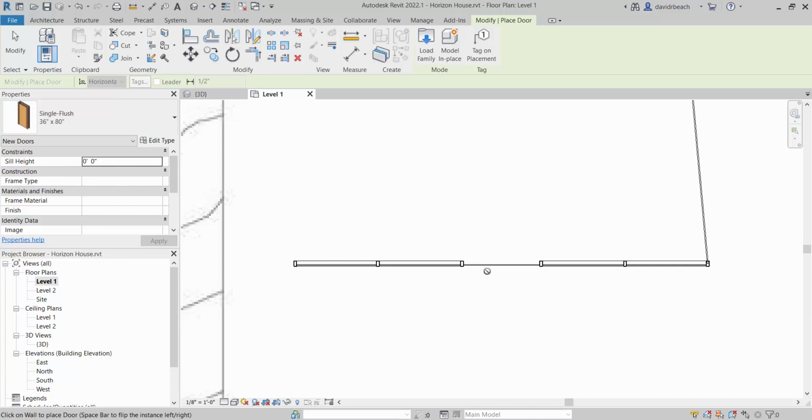Okay, usually if you think about the airlock on our building, those doors in the airlock came from the same company that did the curtain wall door, creating the curtain wall system, creating the airlock. Right? So in Revit, in terms of building schedules, I need a door that's in a curtain wall associated with the curtain wall, not with the standard door schedule. Okay, so it is a different system. It is literally saying, okay, this location is not a pane of glass, but it is a set of doors. That's however it is set up.